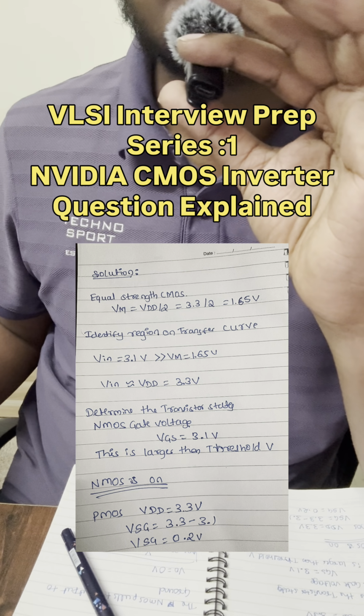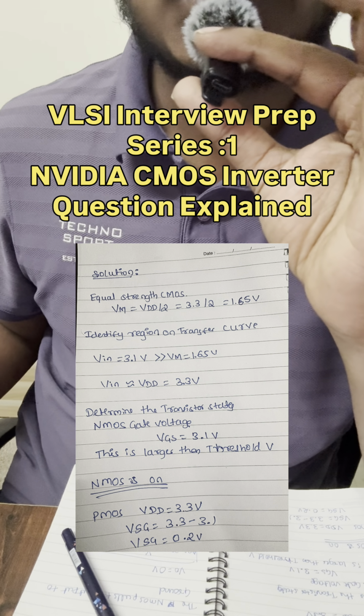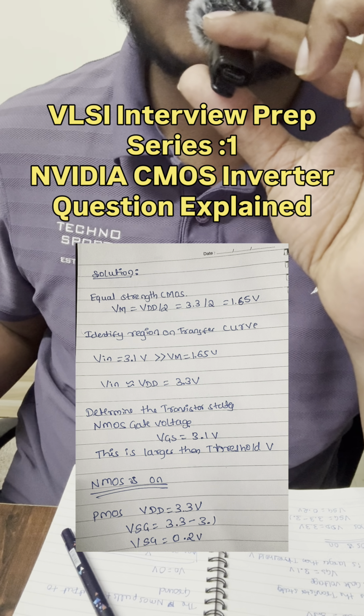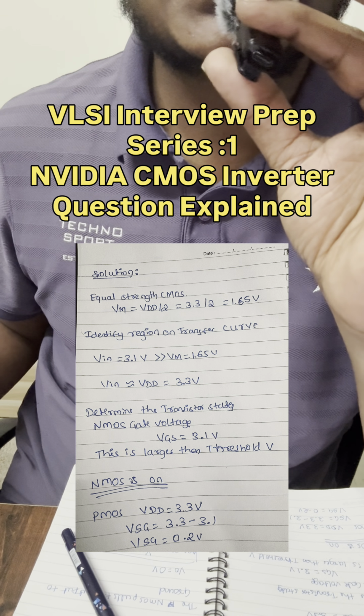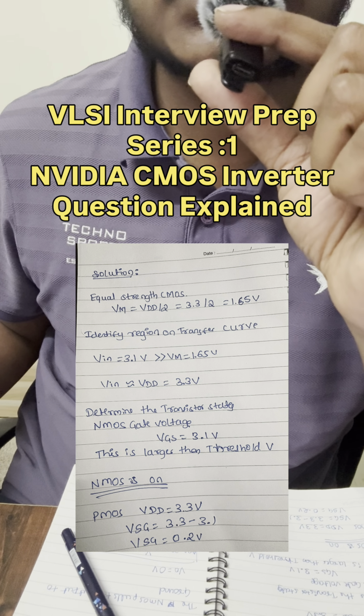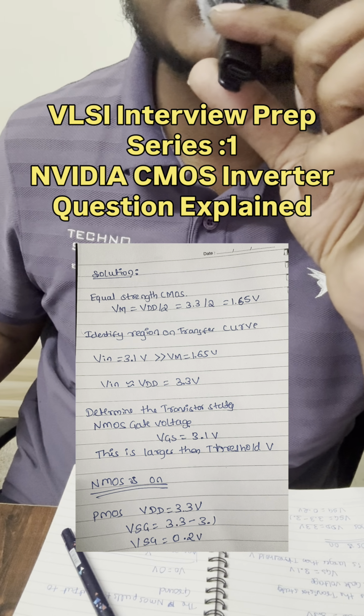When the strengths of the PMOS and NMOS are equal, the switching threshold of the inverter occurs at half of the supply, that is VM is equal to VDD by 2. Since the supply voltage is 3.3 volts, the switching threshold becomes 1.65 volts.